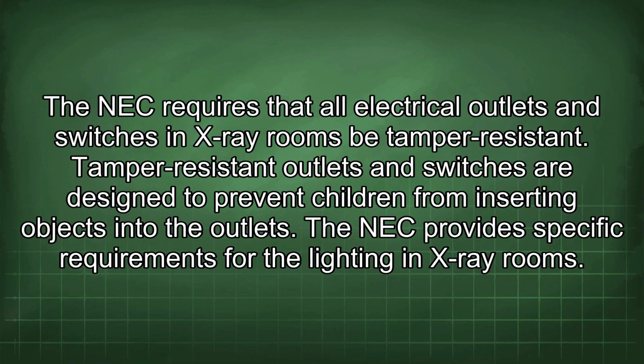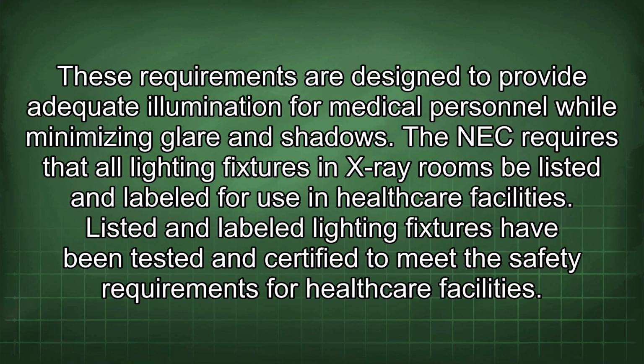The NEC provides specific requirements for the lighting in X-ray rooms. These requirements are designed to provide adequate illumination for medical personnel while minimizing glare and shadows. The NEC requires that all lighting fixtures in X-ray rooms be listed and labeled for use in healthcare facilities. Listed and labeled lighting fixtures have been tested and certified to meet the safety requirements for healthcare facilities.